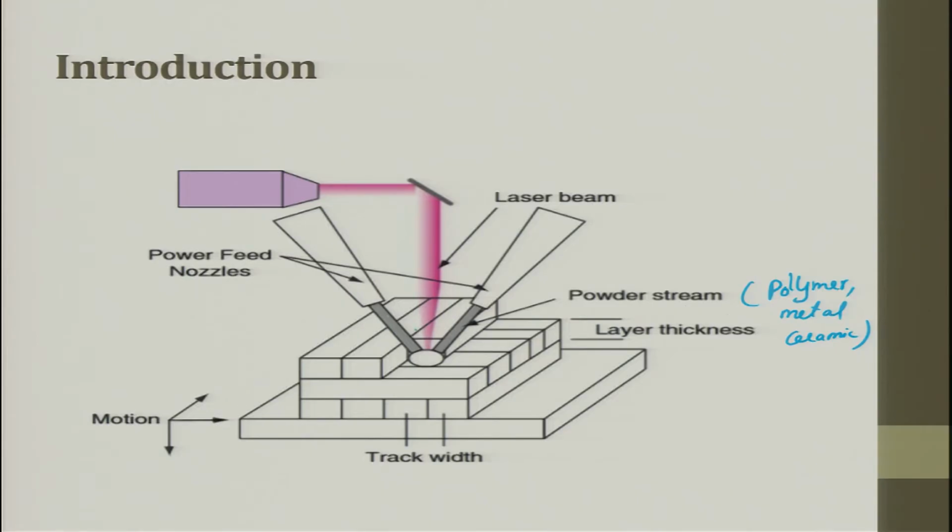You can see here you can have multiple nozzles feeding the powder, and then you have a laser which is in the center which exactly focuses it and then melts it. So, you will have an optic system in between. In the schematic diagram we do not show it, and this is called a galvo stage, which swings and sweeps to get the XY plane data.